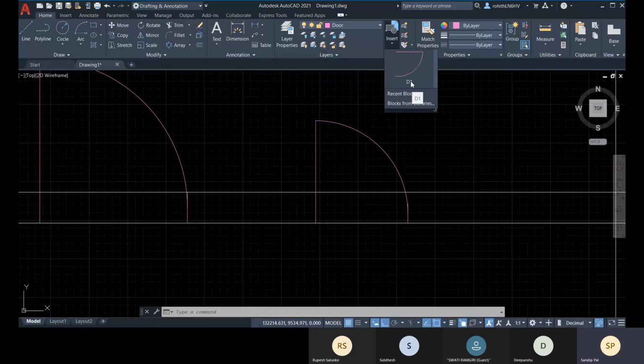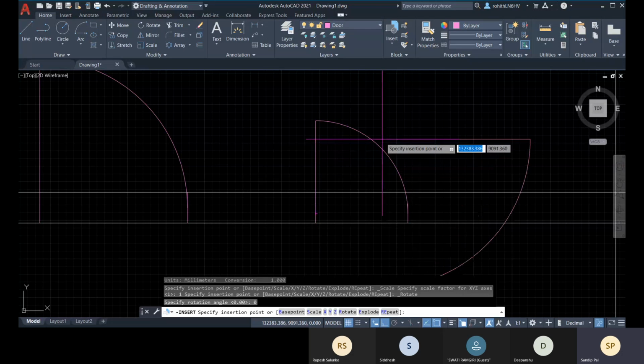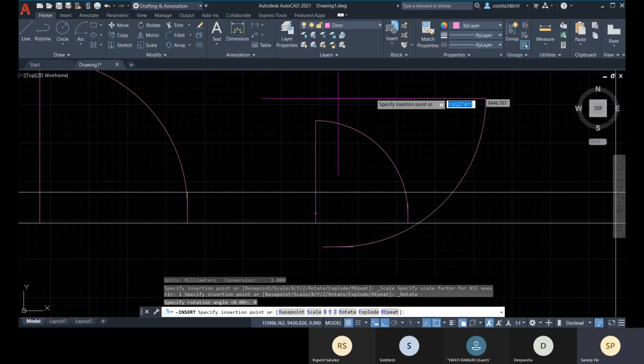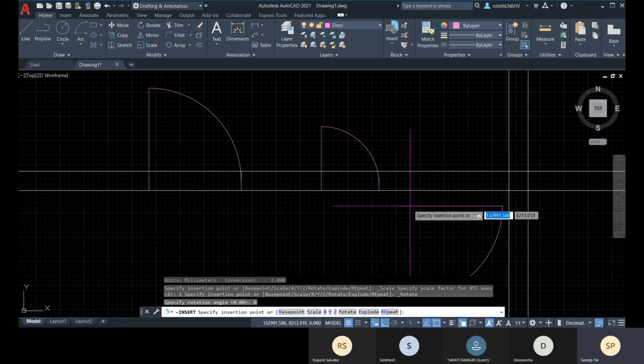So when I choose this scale option, it scales in each dimension. It will scale for all the dimensions. Now, for a window, you will only be changing in the X direction, in the length direction only. Your thickness will be the same. So you will not be applying the scale factor for all the dimensions. For that, you have to specify a particular dimension.